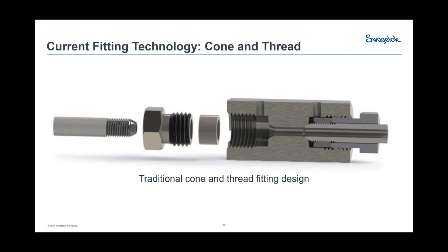One interesting piece about the entire design: if you notice that little hole in the top coming in perpendicular, that's a leak port, and they put that in because they leak. They leak in oil and gas. They leak with small molecule gas. They are really prone to vibration and any kind of side loading on the system because, as you notice, that cone goes into that chamfer and has nothing ahead of the sealing point to control any kind of angular displacement that's being placed on the system.